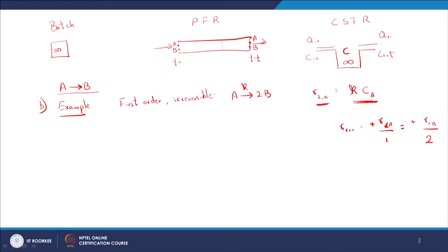That is obvious, because in our mass balance equation, we already have rate of formation minus rate of loss. So, if you again write rate of loss equal to the negative of something, this is going to end up being positive, the second term here. That is what we do not want to have. So, you will just write rate of formation minus rate of loss, and we will just write the magnitude of that rate of loss, which in this case is Kca, right.